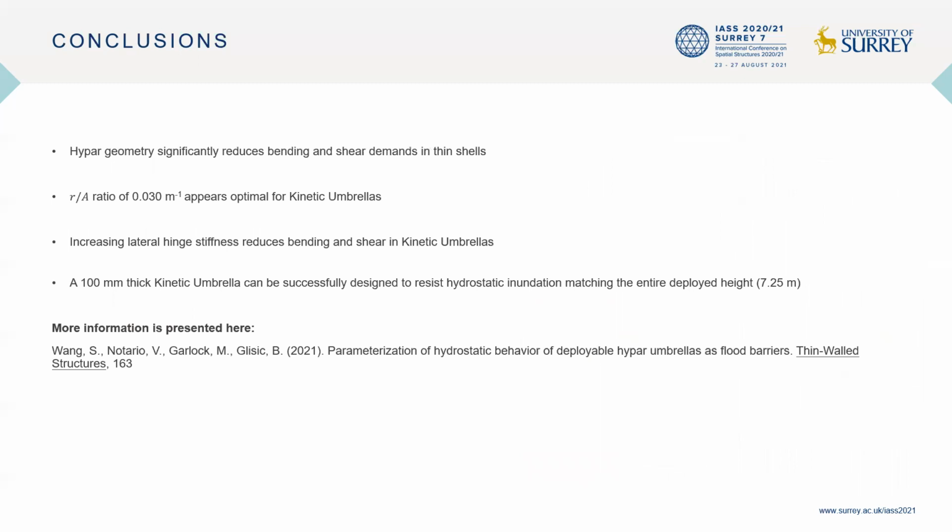In conclusion, it is demonstrated that hypar geometry can significantly reduce out-of-plane bending and shear demands within thin shells. In the context of kinetic umbrellas, an R/A ratio of 0.03 inverse meters appears to be optimal. In addition, increasing the lateral stiffness of the supporting column acts to further reduce bending and shear demands within the shell.